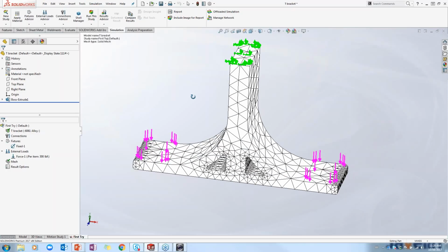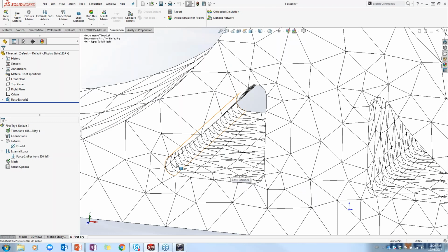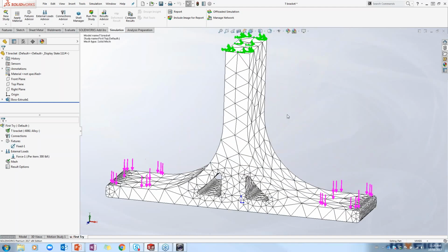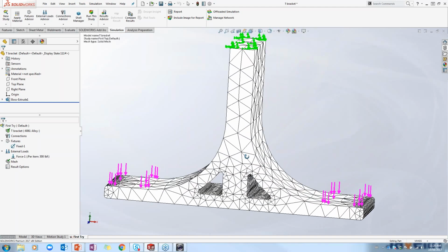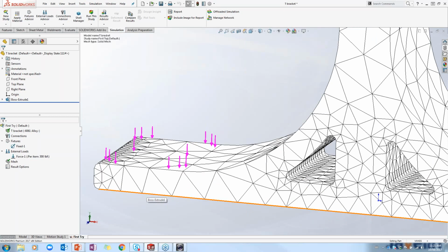This is what it looks like. It took a couple seconds there and my screen flashed, but it's gone in and meshed the part. What that curvature-based mesher will do is automatically refine around fillets, around curvature regions, places I'm going to need a finer mesh. Now, we'll talk more about results in a moment, but this does not really look like a refined enough mesh to me. There are ways we can troubleshoot this, but really you need at a minimum a couple of elements, 2 elements going through the thickness of the part.